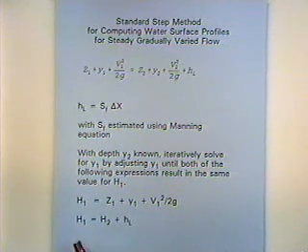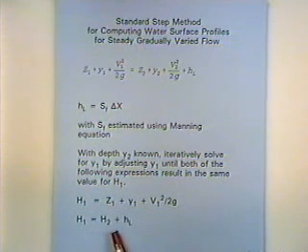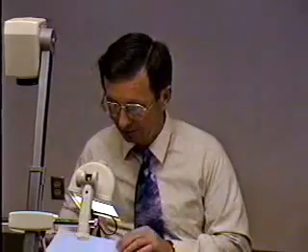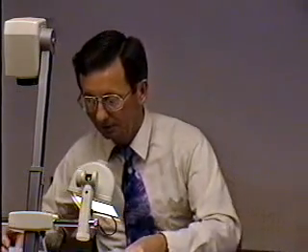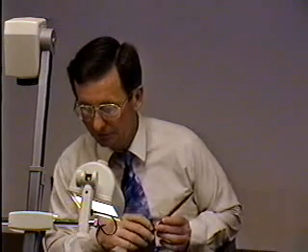And also, the head at the upstream section is equal to the head at the downstream section plus the head loss in between. So both of those expressions are true. And so we've got to set up an algorithm to do that. And the number crunching gets a little time consuming here. So hopefully, and it would seem to reason what they would do on the exam, is to give you a prismatic channel, something that's easy to work with, like a rectangular cross-section where you can use the direct step method.